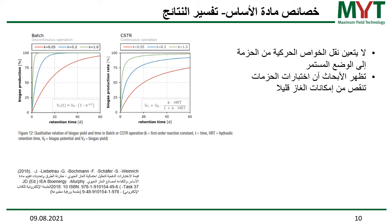However, at the end you have a gas potential here, and in a CSTR you obtain, as I already said, only a yield if you run a CSTR system at one retention time. If you want to obtain the gas potential, you need to operate several digesters at several retention times, and then you can calculate this curve you can see here based on these points. Again, it's not possible to transfer kinetics from a batch test to a CSTR system.